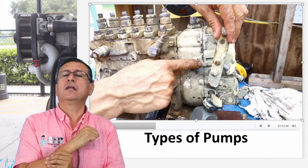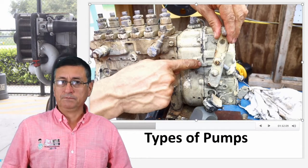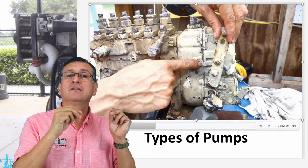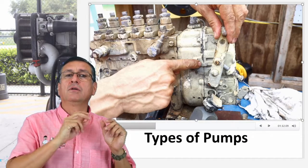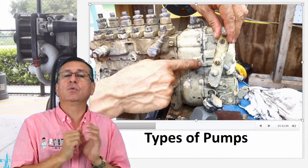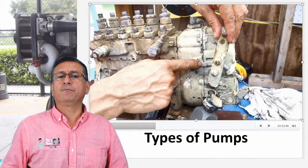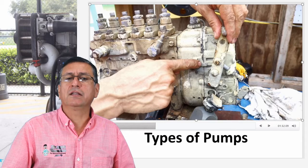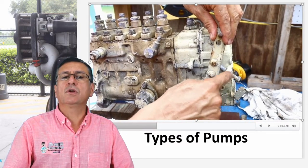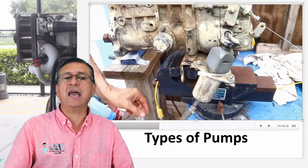1500 RPMs. And the RPMs for American generators? 1800 RPMs. In those generators, you need to fix the bolt for idle and the bolt for wide open throttle in order to keep the acceleration constant. Okay, this is the bolt for idle, and this is the bolt for wide open throttle. All right, you can adjust both bolts, and this is the solenoid to stop the engine.